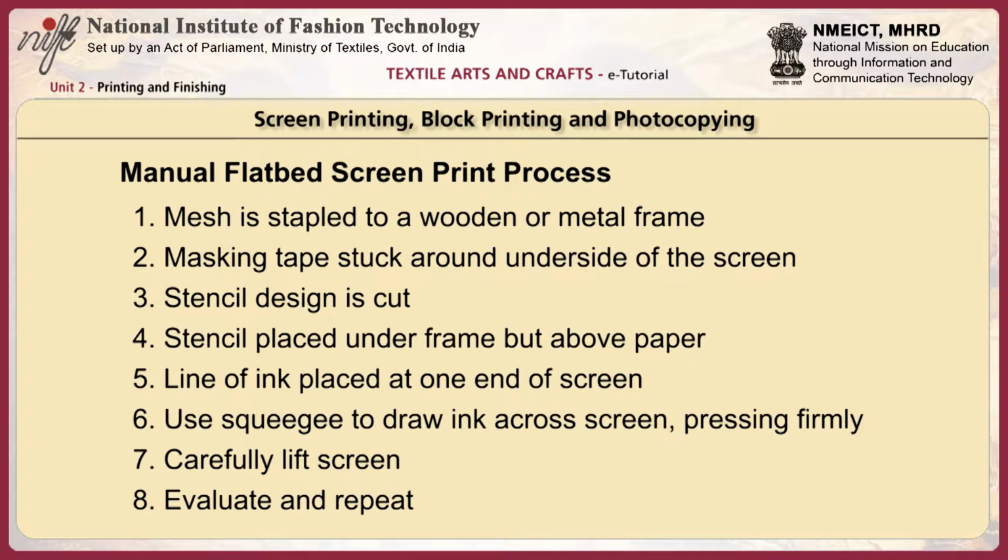Use squeegee to draw ink across screen, pressing firmly. Carefully lift screen. Evaluate and repeat. Screen printing is used to print small runs of posters, display boards, fabrics, wallpapers, and control panels of electronic product.